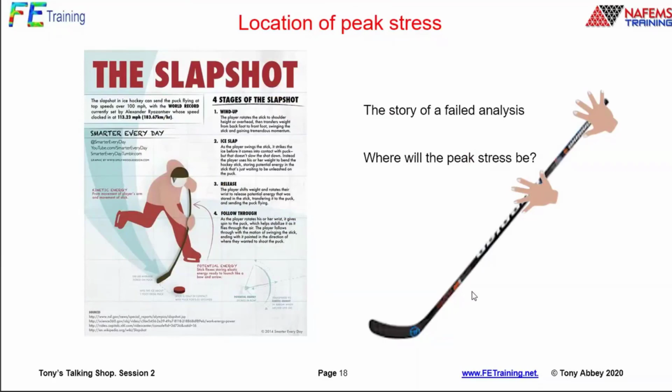Cut a long story short, we submitted this to the company. The managing director loved the opposition's result because he said, well, on test, that's where we get a failure right there. And we were kind of puzzled. I phoned up the technical director and said, well, what's going on here? He said, well, we didn't tell you there's actually a splice in there. So the splice generates the stress concentration. And that's actually more of a fabrication failure at that particular point. But none of you knew that.